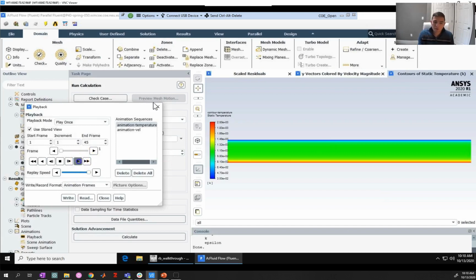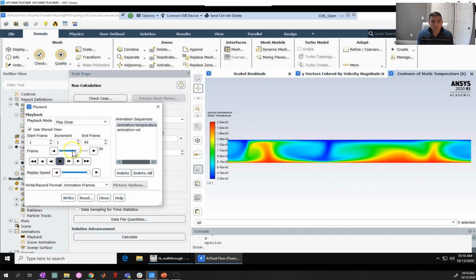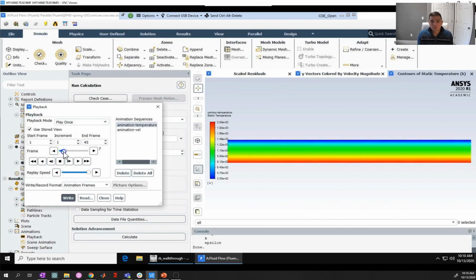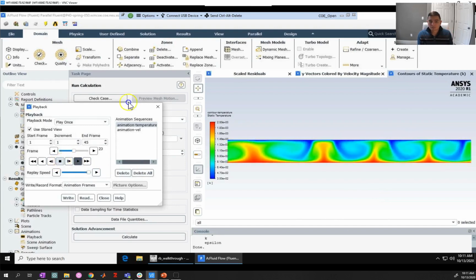So let's go ahead and take a look at this. In the initial portion of the simulation, we can see that the boundary layer of the temperature increases, but eventually we see some instabilities occur where we get patches of high density fluid falling in what's called a plume. So this is a small narrow filament that falls from the top boundary to the bottom boundary. Eventually more and more of these filaments start to grow, and these instabilities grow over time, causing the system to destabilize and eventually forming large overturning patterns.